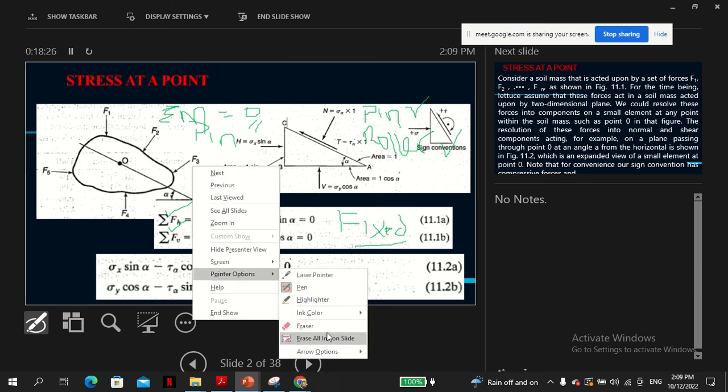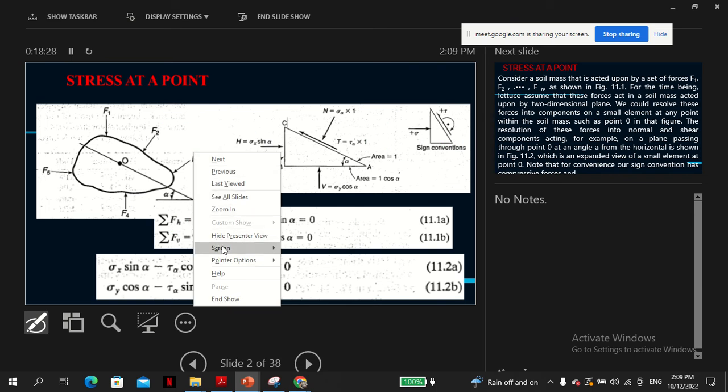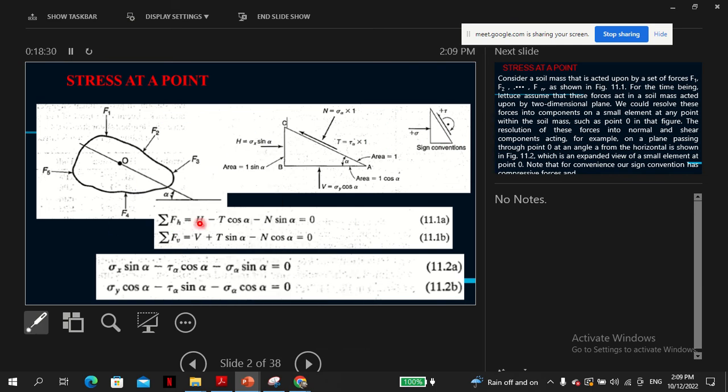I hope that's a sufficient explanation. Here we are supposed to use the three equations, but because of the support condition of the soil, the moment forces do not exist. In other words, we assume the soil cannot take moments because of the nature or the way the soil is. So that's why we only use these two forces.